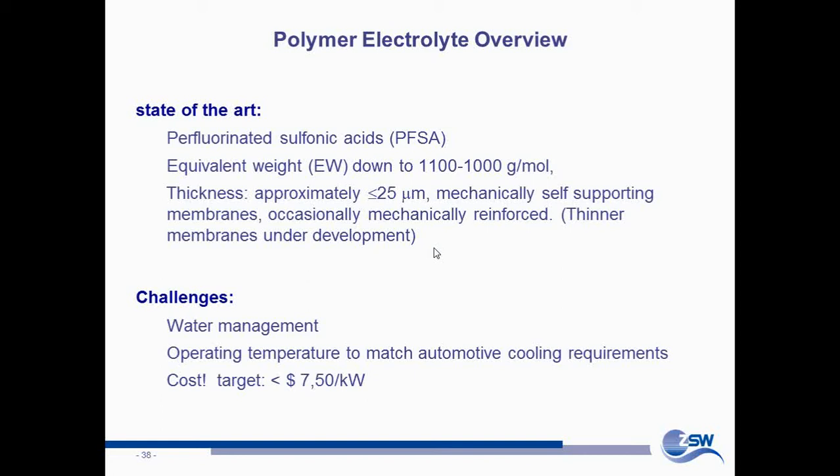But being from the practical fuel cell developers end, we typically sustain a highly hydrated situation in the polymer membranes. So we don't care too much about small polaron hopping and stuff like that. We typically try to rely on the faster mechanisms like the Grotthuss and like the typical ions in motion by diffusion.